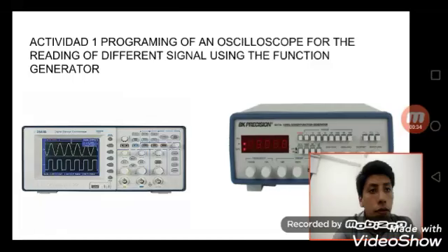Well, the function generator simulates and creates different signals or waves, for example, a square wave, triangular wave, and sine wave. In that way, we can analyze various parameters, for example, the amplitude, period, and wavelength. Related to aeronautics, it is used for avionics navigation equipment tests, for example, onboard ILS, DME, and ADF.